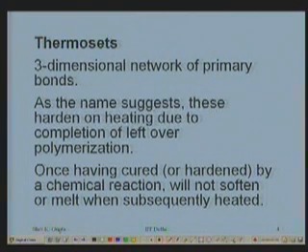As the name thermosets says, thermo means you heat, sets means it hardens. So as we heat, it hardens. It hardens because any leftover polymerization goes to completion with the available thermal energy from heating, and it becomes a complete single molecule, a three-dimensional network.